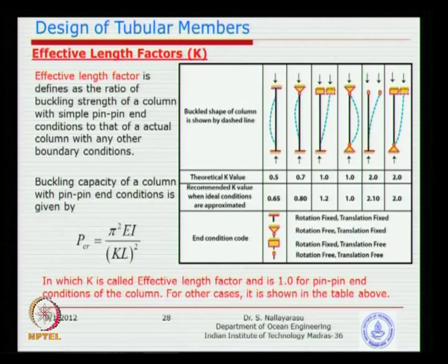You know very well, if you have a beam vertically supported, for sure translation is restrained, but when you apply a load, if the beam is rotating at the ends, because it is only an edge support not encased into the support itself, then the rotation is going to happen. But at the same time, if you hold the beam for a sufficient length by a clamp or by an encasement, the rotations are not going to happen. It is called a fixed support. So, it is all how the construction is done, you have to reflect them in the design.